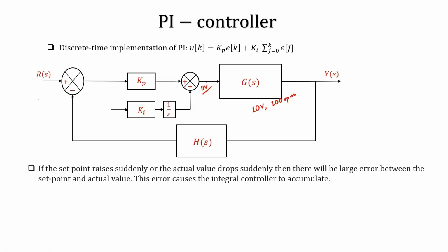The other case can be that the system is such that after 10 volt the motor does not even respond to whatever input you are giving. In that case what will happen? The motor will be stuck at 100 RPM because 10 volt was giving it 100 RPM. After 10 volt, whatever you give doesn't matter because the maximum speed will always be 100 RPM.